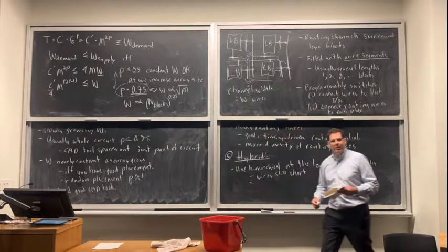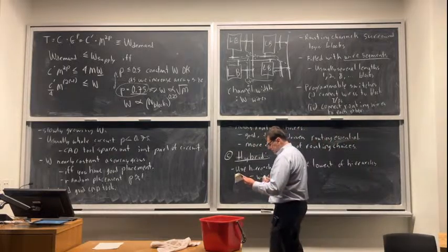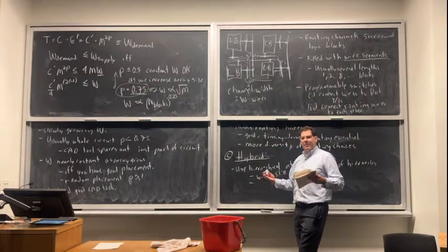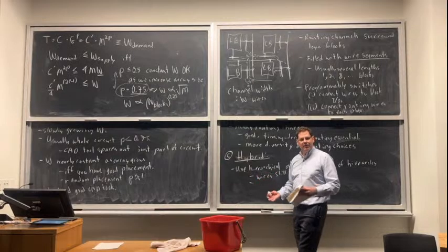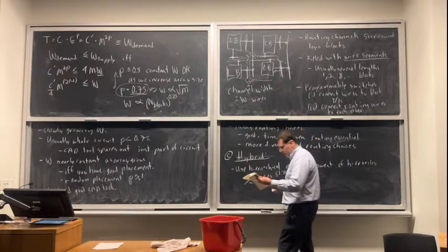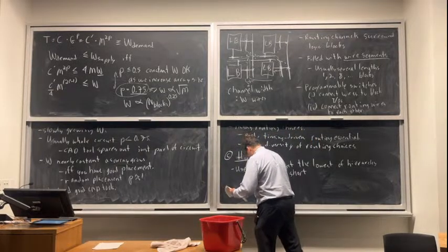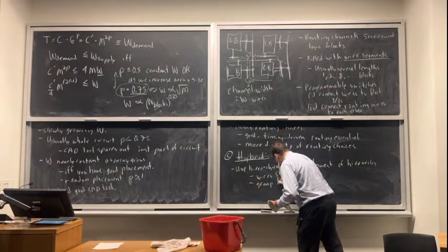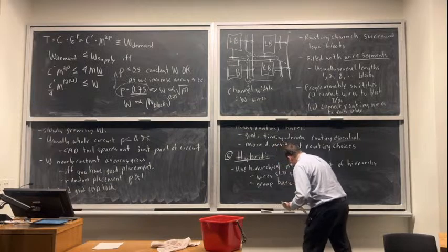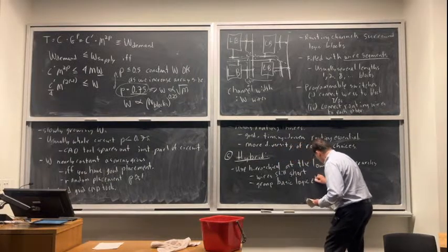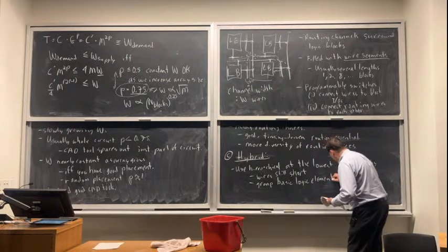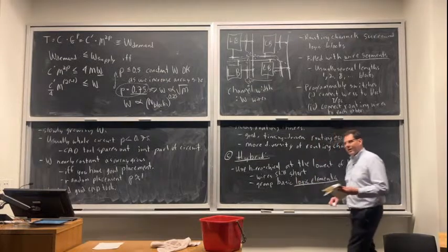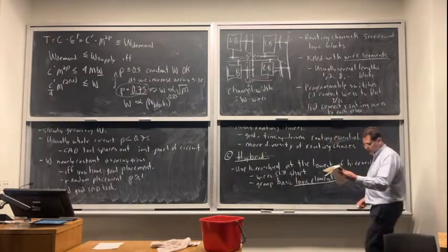And what we do is we group what the academic community often calls basic logic elements. It's just like LUTs and flip-flops, basically. So we group little bits of logic. Okay, so those logic elements are the LUT plus flip-flop that we had before.